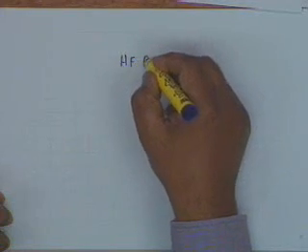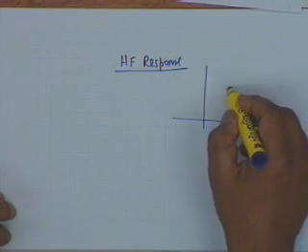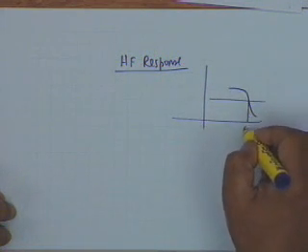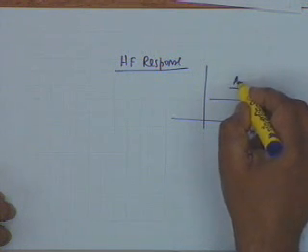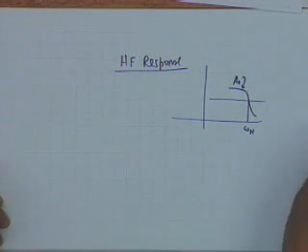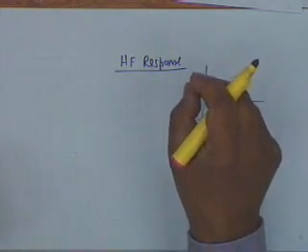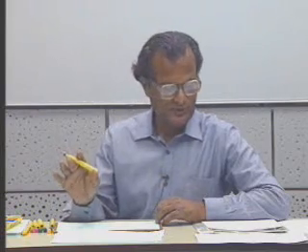Alright. Now, so far so good about mid-band and low frequency. What do we do at high frequency? How do you determine, at high frequency, as you remember, omega H, and this is A0. How do you determine the high frequency 3 dB cutoff? At high frequencies, the Cc1, Cc2 and Ce, all of them are shorts. What is effective is the internal capacitances of the transistor, that is C pi and C mu.